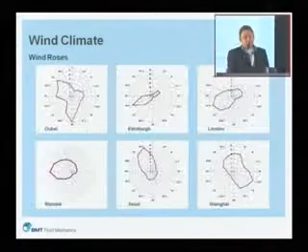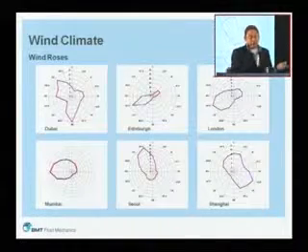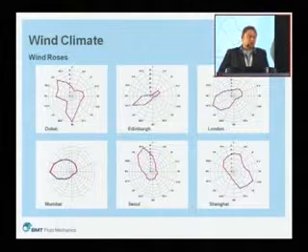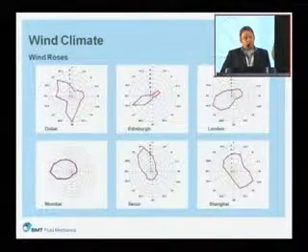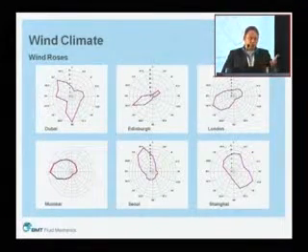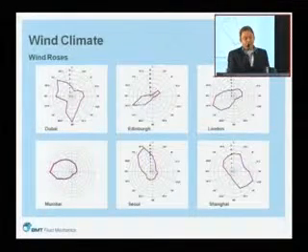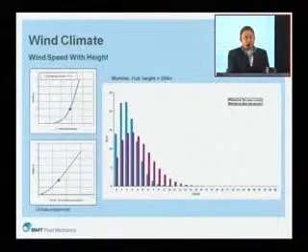These graphs show wind force. The other thing you obviously need to consider is directionality of wind. We had an example before where the wind turbines, when integrated into a building, were favorably aligned with the prevailing wind direction. So that's telling you that most of the time the wind turbines will actually be seeing wind through them. And again, that's quite key to the final number of your energy yield.